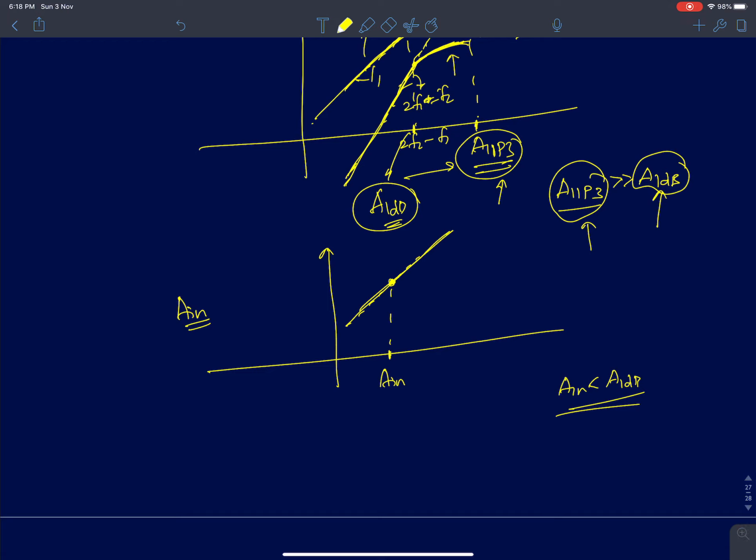And then at the same point, I'll also try to find the third intermodulation term, the IM term at the same frequency, the power of the intermodulation term. So when you run a simulation, a two-tone test, you can easily find this for some small input signal level. Now let this power difference, the difference in two powers, be delta P. This level minus this level.